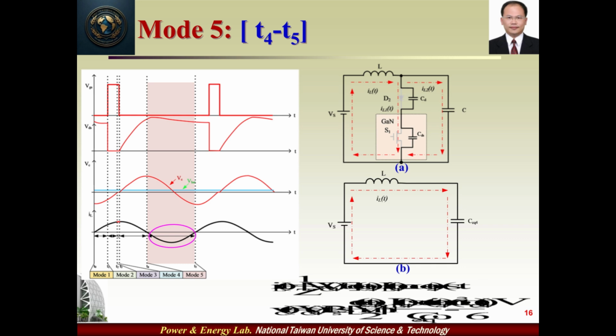In this mode, the sinusoidal loading current is reversed to a negative value by using resonant behavior, that is to say, it starts to recycle energy to the battery module. As you can see, when T equals T5, the resonant inductor current IL,T resonates to 0, this mode is ended, and a complete cycle analysis is also finished.